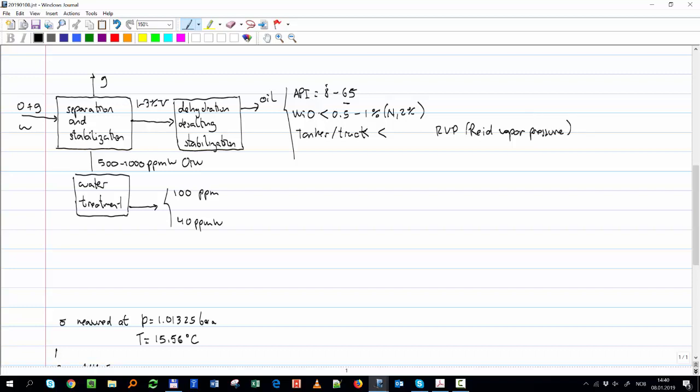Should be below 11 psi A. Okay, and that, in a simple way, we are going to go. We have to talk about phase behavior. We have to talk about different things to see what this vapor is. But basically, if I lower to 11, that's the point where some still gas comes out of the oil. Okay, it still has some vaporization of gas. Think about it. It's not exactly that, but think about it in that way.